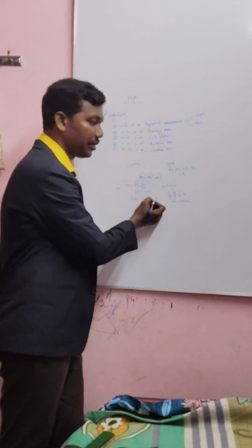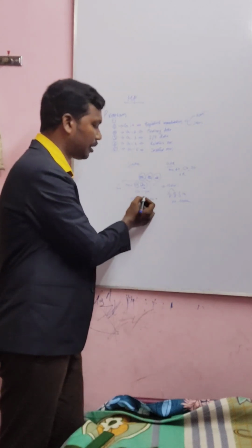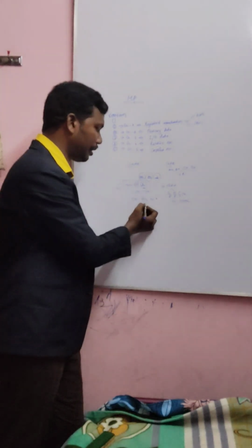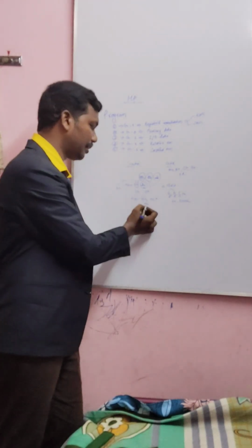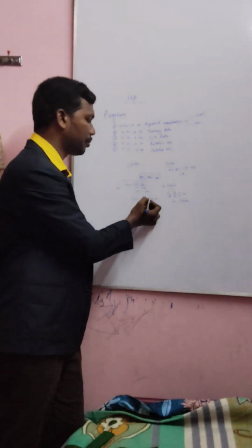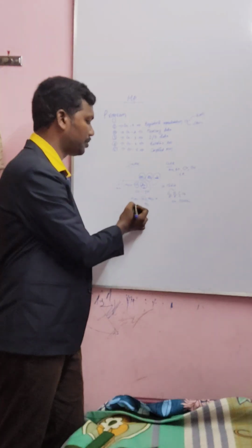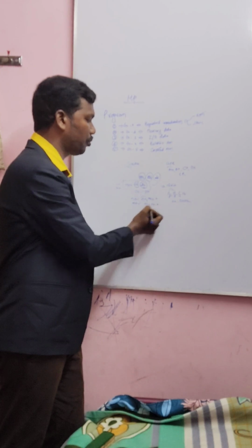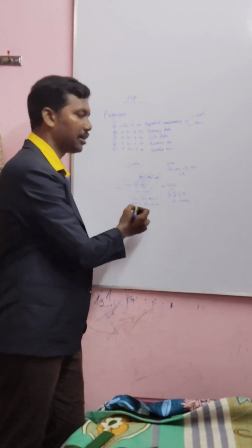So either you can use 02 with AL or AX. AL is enough for keeping 02. If you are using AX, you represent 0002. So the same instruction, 8-bit and 16-bit, will be MOV AL, 02H. So what is the meaning of this? This is an immediate addressing mode.